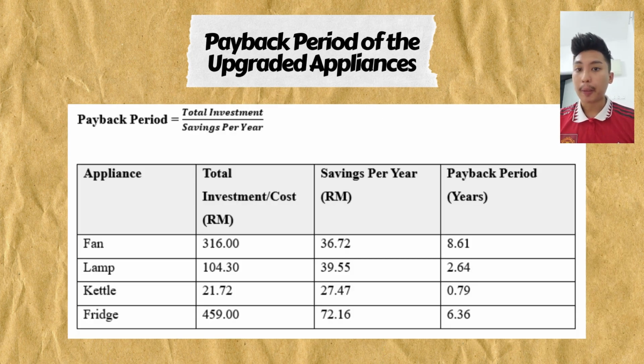Finally, I've analyzed the payback period of all 4 appliance upgrades. Payback period makes it easy to calculate how long it will take for the cost of an appliance to be returned through energy savings. In other words, this is to assess whether the investment is really worth it or not. The payback period can be calculated using the formula shown here, which is total investment divided by savings per year in ringgit.